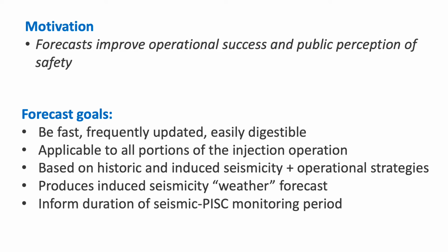These forecasts should be fast, they should be able to be produced and updated in near real time, and they should be easily digestible by end users. Additionally, they should apply to all periods of the operation, including before, during, and after an injection operation. In general, we will use combinations of historical seismicity, observed induced events, and operational procedures to produce something like an induced seismicity weather forecast. Information used to generate these forecasts can then be used to inform the duration of the seismic post-injection site care monitoring period.